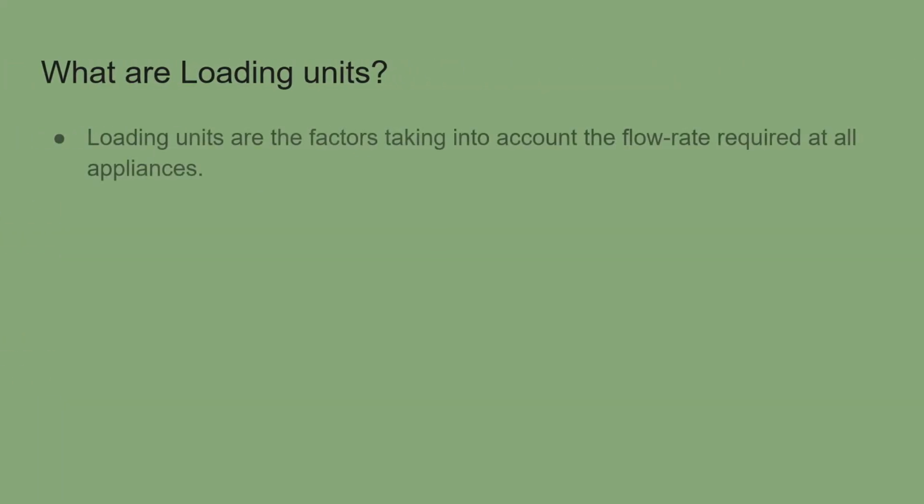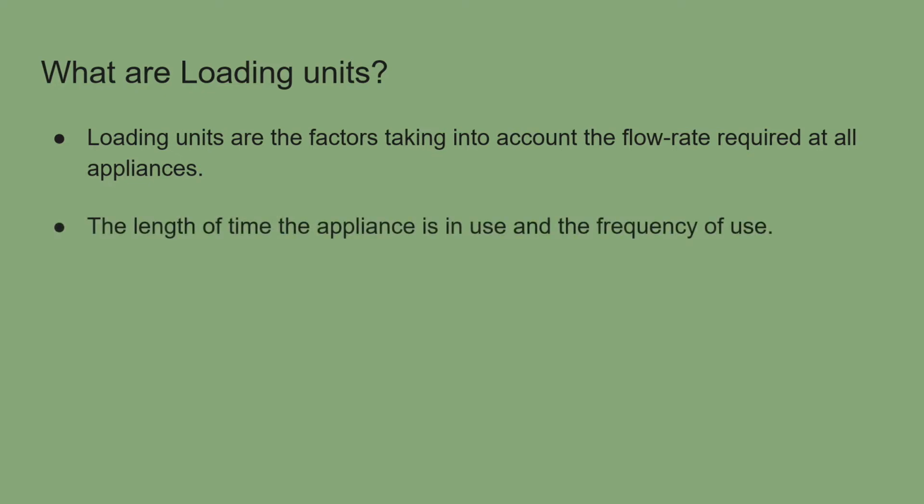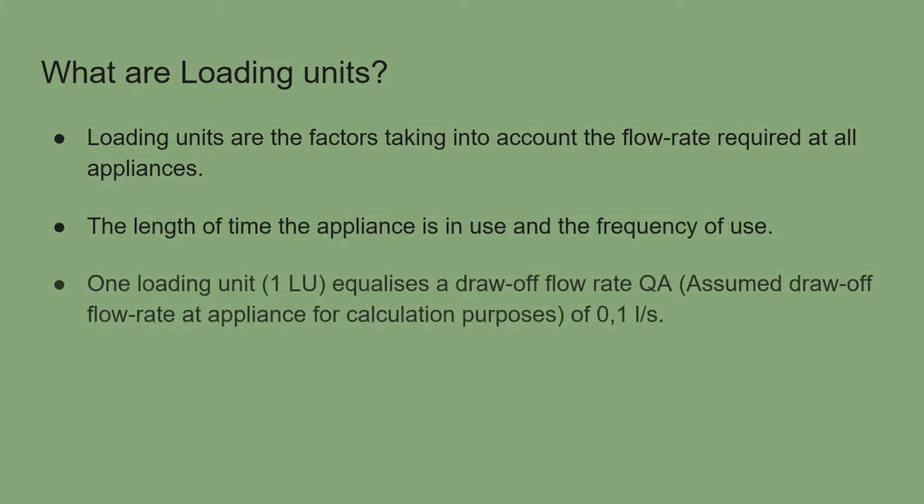Now, what are loading units? I've already mentioned it. Loading units are the factors taken into account: length of time the appliance is on, frequency of use. So we've got one loading unit is usually 0.1 litres a second.